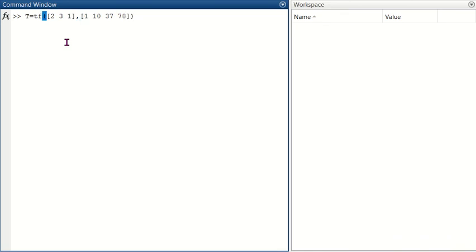So this forms the transfer function of the system, and of course we also learned that whenever we draw a root locus, we consider that there is a design parameter, abbreviated as k, which is introduced to the system. Since this is the transfer function of a system before introducing the design parameter, the command rlocus considers the transfer function of the system without the design parameter introduced.